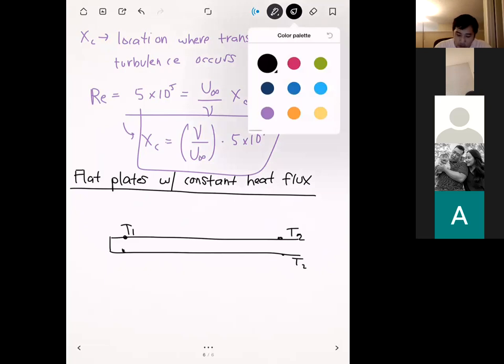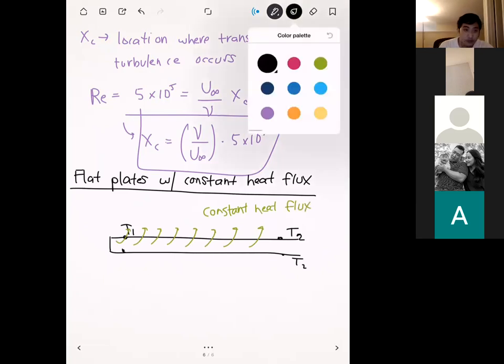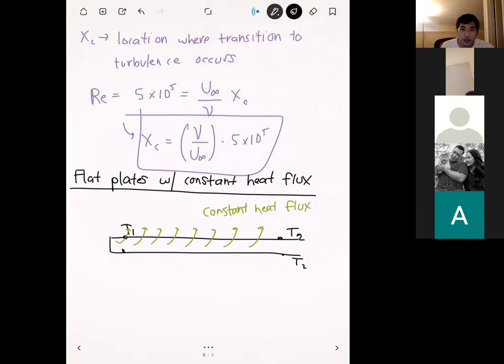Okay. And so I would say the Nusselt number correlations that I'm going to give you now are probably a bit more common from what you would expect from a fin, because oftentimes for a fin, you have a pretty long surface, and you're not going to have the same temperature all throughout. But what you can assume is that the heat flux might be constant all throughout. Okay. And so in those cases, this is basically going to change your Nusselt number correlations.